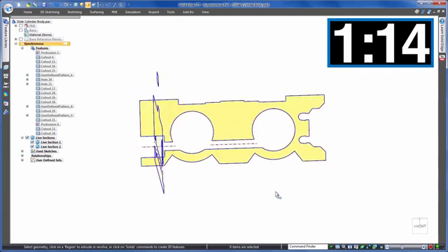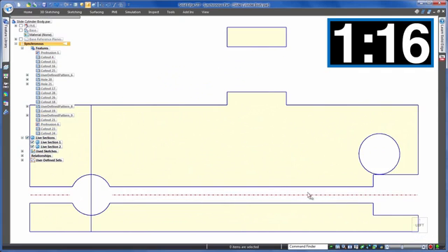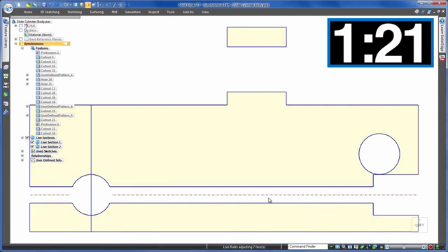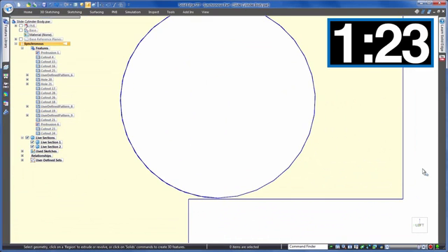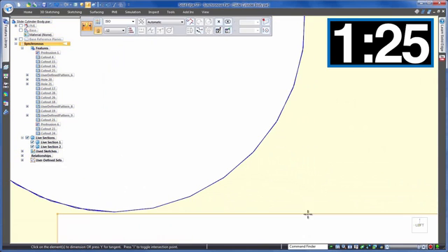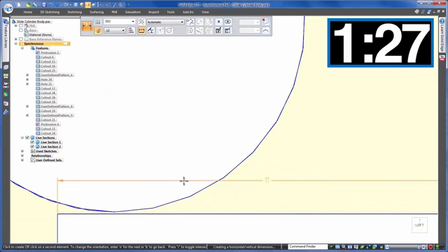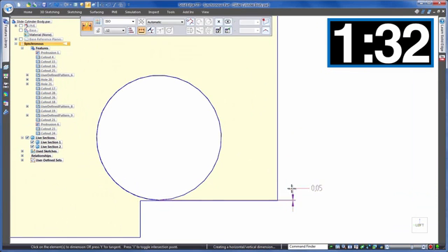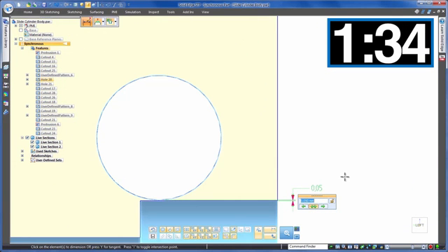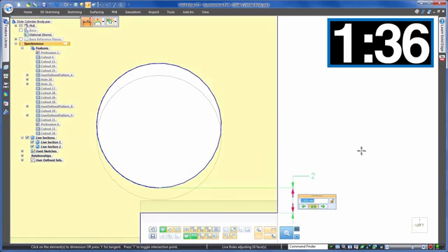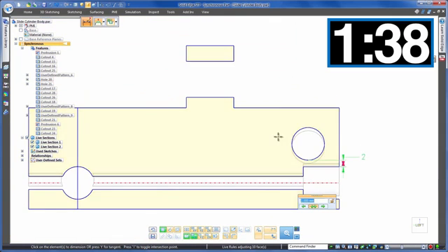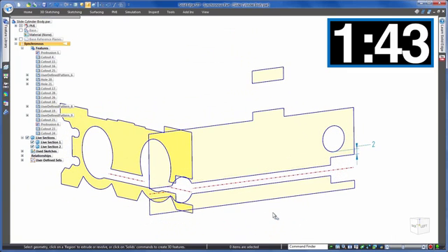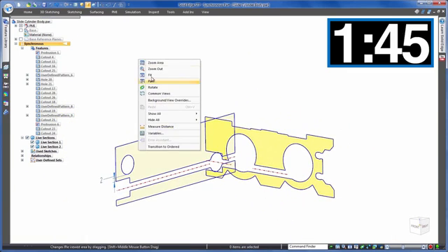We can then simply drag this profile to see how the design intent is being taken care of, which of course is modifying all of the solid geometry in the background, or use precision tools to make the edits. We use the same dimension tool we've been using all along to add 2mm, or round to 2, as we can now more clearly see the overall geometry. But what about that rear counterbore? Well, no problems here. Solid Edge has recognised the design intent of keeping these aligned, and of course you have the freedom to intervene if you wish.